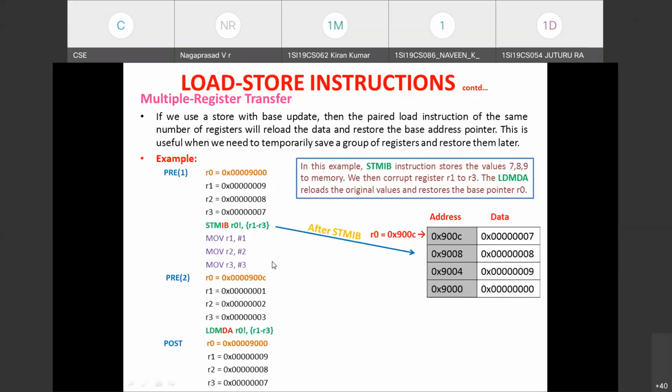Remember, in general, IA, IB, if you are using it, moves from lower register to higher register, since we will be moving from lower address to higher address. See, first address is updated to 9004. At this address, 9 data is stored, which is R1 register content. Next, the address is incremented, and then the data held in R2 register is saved. And again, the address is updated to 900C, where R3 register content is saved. Okay, this is what happens when STM-IB instruction is executed.